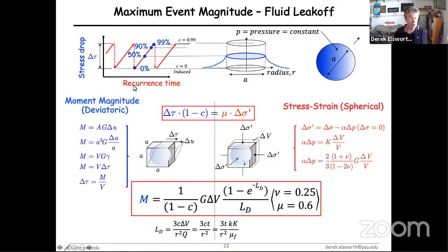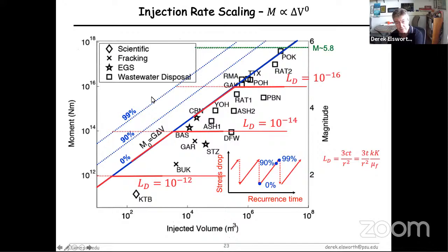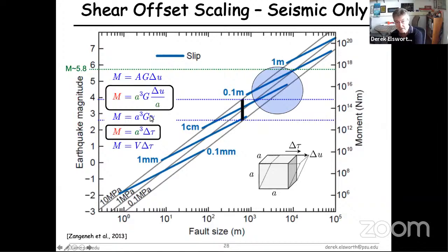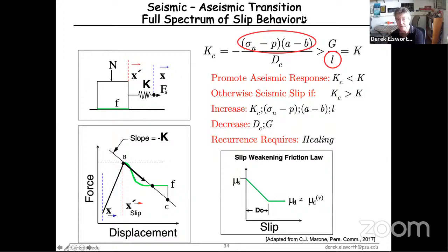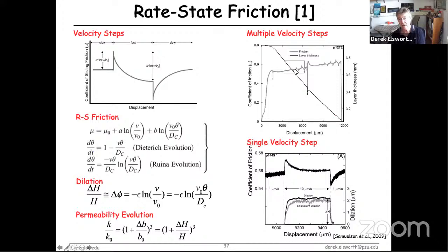So it is broadly used in the earthquake physics community, just because it really accommodates most of the observations of field behaviors. Certainly, as we mentioned in the presentation, it accommodates not only the deformation behavior that you see, but it also accommodates, for instance, dilation for a particular figure, like that in this figure. And so not only does it pick up the changes in deformation that occur in terms of strength loss as a function of shear, as you do these experiments by perturbing the strength, but it also picks up dilation, which goes to a steady background dilation as you get steady state shearing. This is a steady state shearing velocity occurring with displacement. So it picks up most of those influences.